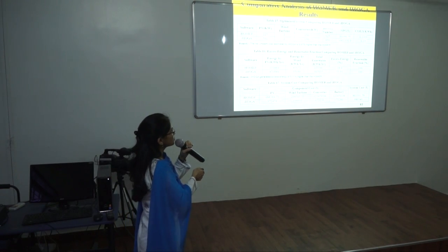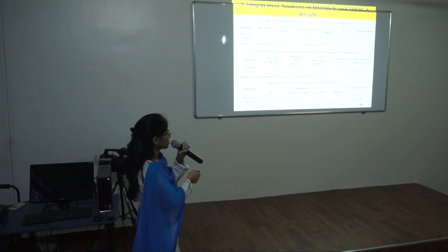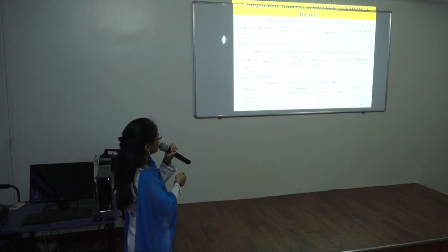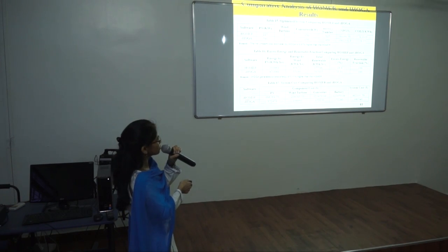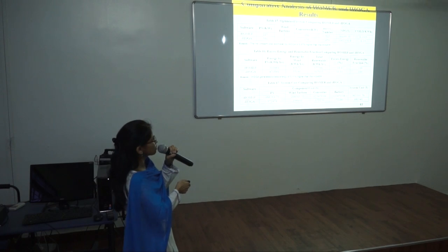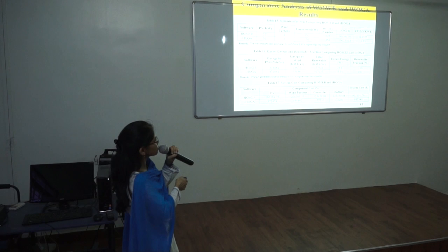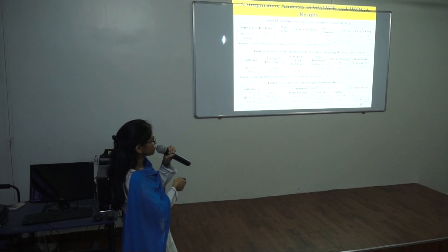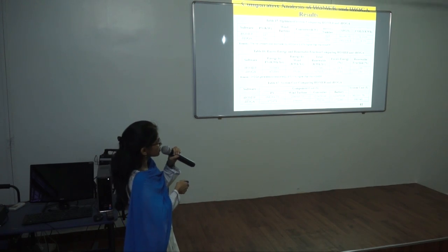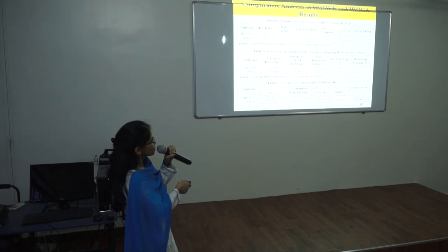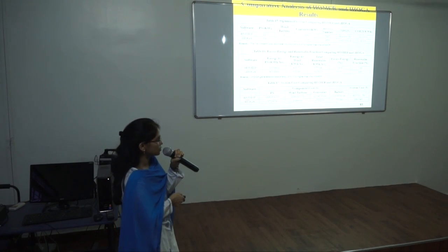The second comparison is based on electricity produced by the renewable system, renewable energy fraction and excess energy. The system predicted by Homer will produce total renewable energy of about 377,541 kilowatt hours per year, out of which PV contributes 333,869 kilowatt hours per year and wind contributes 43,675 kilowatt hours per year. The excess energy generated by Homer is about 28.8% and the renewable fraction is 100%.